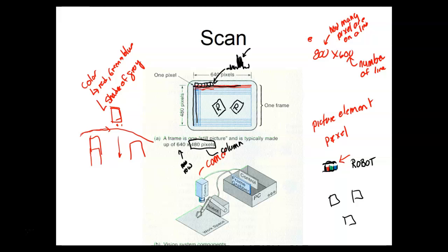So we have a calibrator that we can put down out there. It's a certain pattern. I wish I'd have brought it over. I'll try to remember to bring it next class. You put it under the camera, and the computer inside the camera knows that pattern, so now it can adjust the focus and get the size and the focal lengths for the camera. Then you put the item you want it to recognize out there, and you tell it to recognize it.